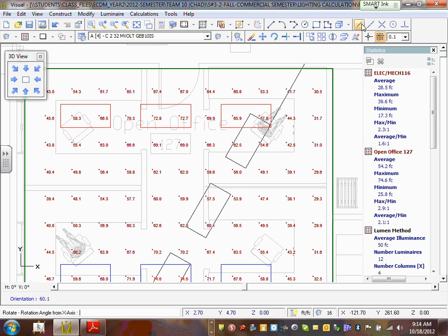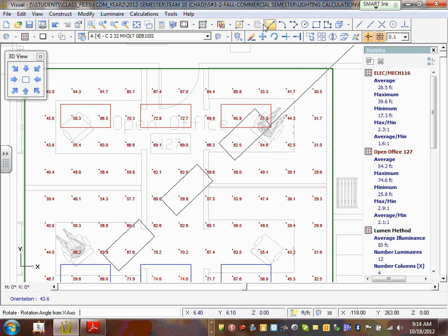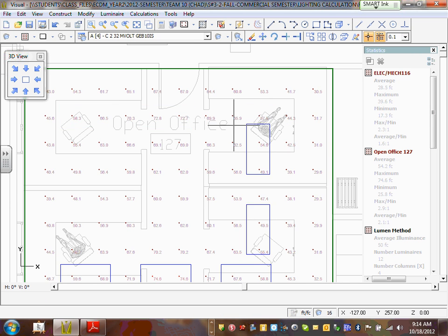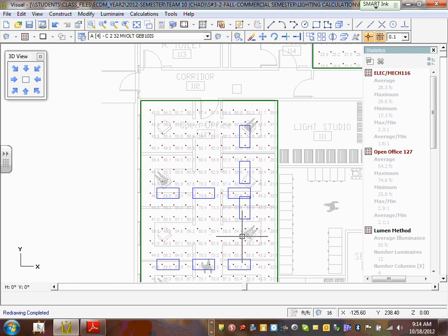And here's your rotation. Put your ortho on. Can you guys see your ortho? Put your ortho on, and here's the one set. And you go flip them. You can flip them, rotate them, and adjust them. So if we didn't, because like his, it came out the opposite way. How do you do it from the get-go?